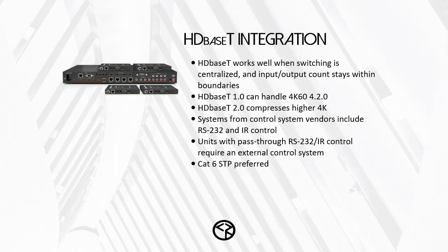So you have noise from the adjacent cable, noise from other foreign sources can affect the quality of that signal and cause problems or reduce the distance that you can go. So many integrators, when they're installing a system, use Cat6 cable or 6A cable to eliminate the problem with noise over distance and adjacent cables.